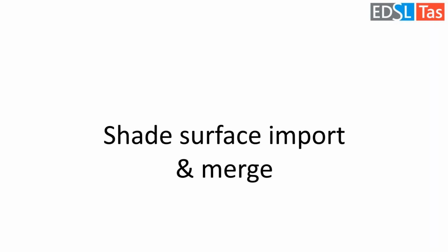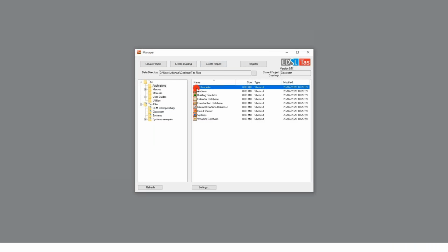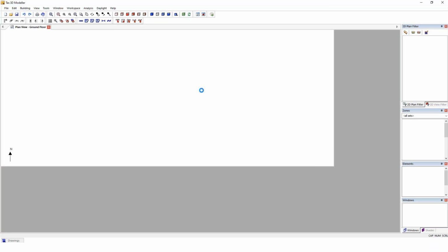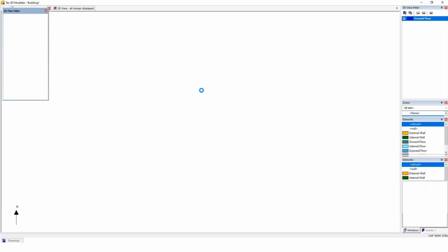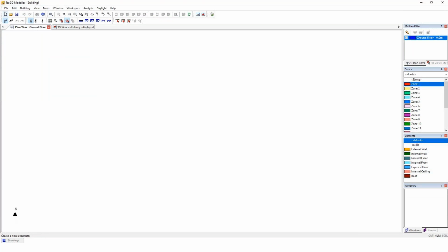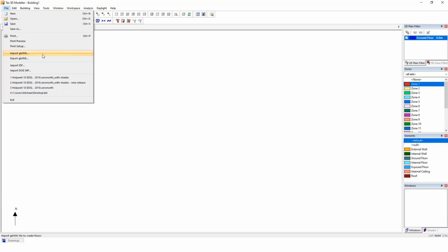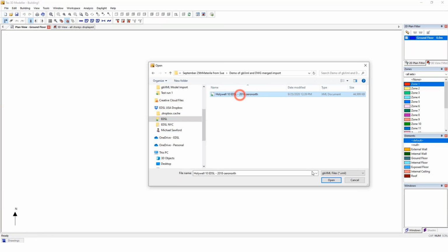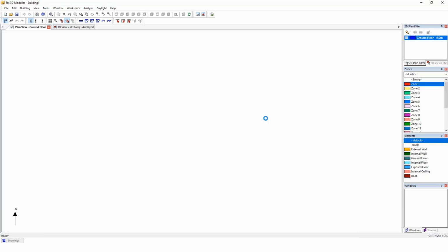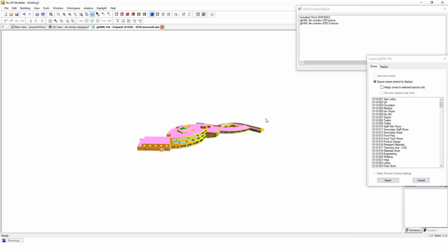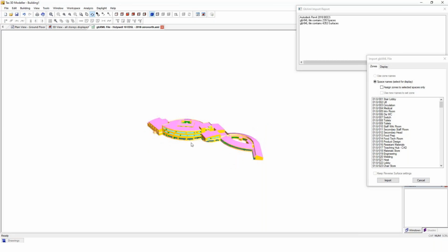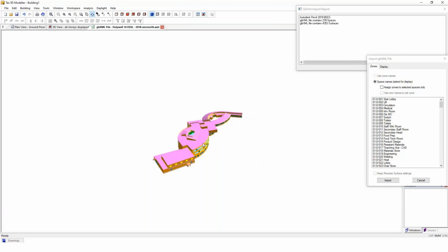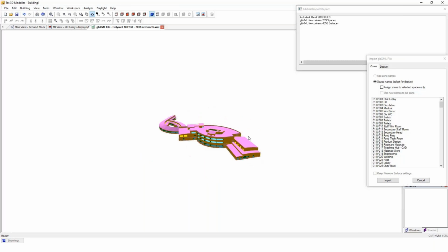So in this, we're going to start in the same manner, opening up our 3D modeling application and importing a new gbXML for a different project. This one's a bit more complex in geometry. So we'll go here, navigate to pick the gbXML and import the file. Here, and then we have the preview come up with all of the spaces on the right, and just navigate around so you can get a feel for the geometry, what's included.